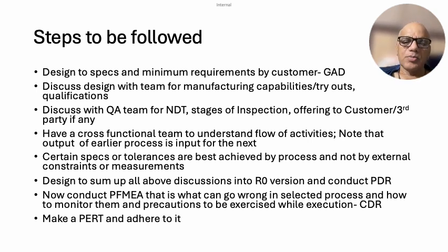But there could be some deliberate pre-cambers or deliberate distortions or deliberate material removal, or keeping it extra, which will be maintained based on our experience and certain data we have discussed in the second and third points, based on some tryouts or mock-ups.